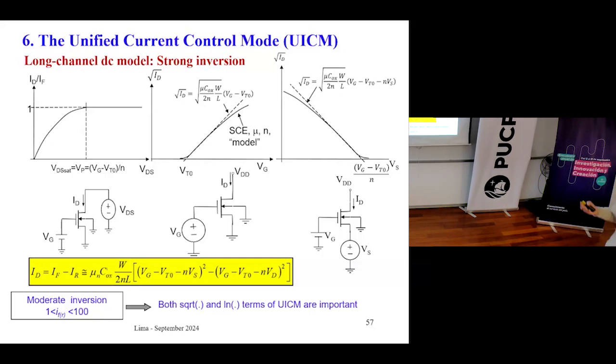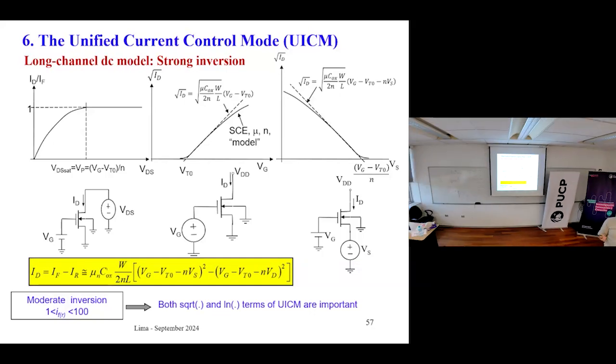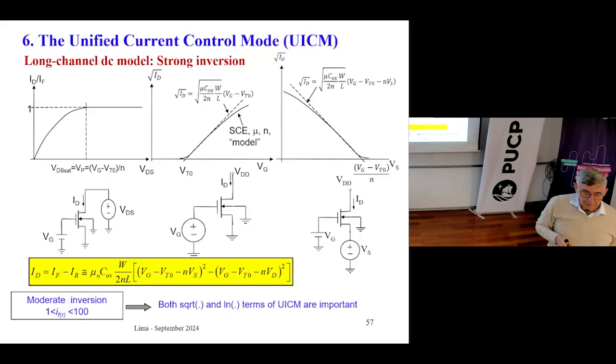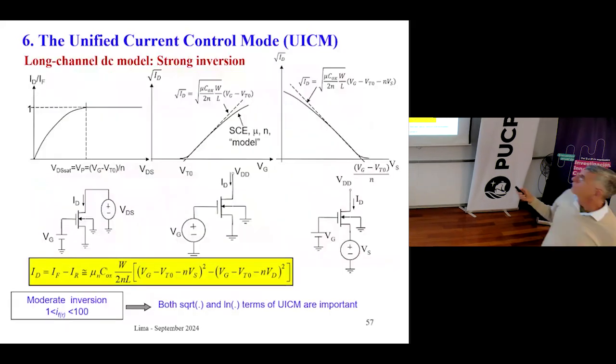So in the past, they used the strong inversion model to determine the threshold voltage. But the strong inversion model doesn't fit all the operating regions. It's just a small region. And what should be the interpolated straight line, here or here or here? You have differences. How do you choose the point where to extrapolate the curve down to the threshold voltage? So this should be avoided, right? There are several methods to determine the threshold voltage. They give some differences, but they give the approximate value of the threshold voltage.